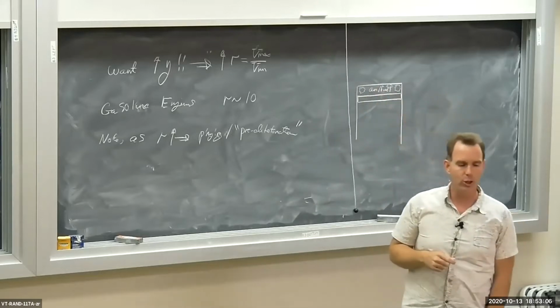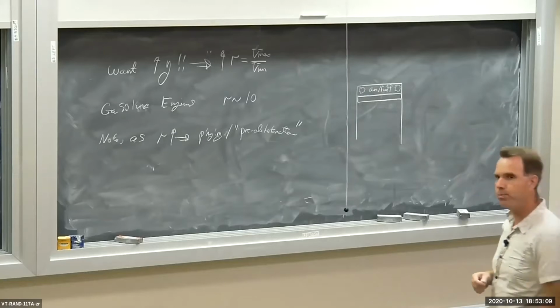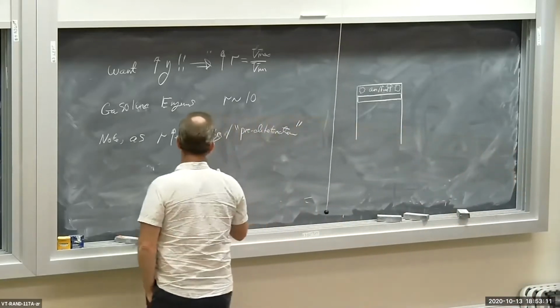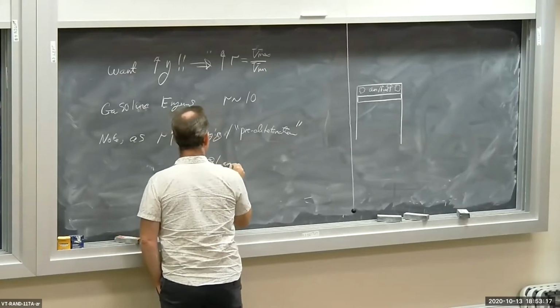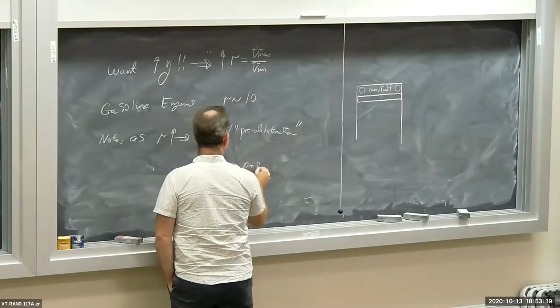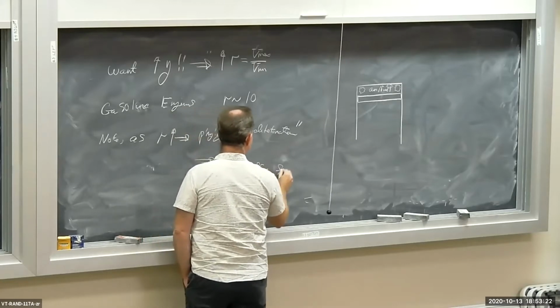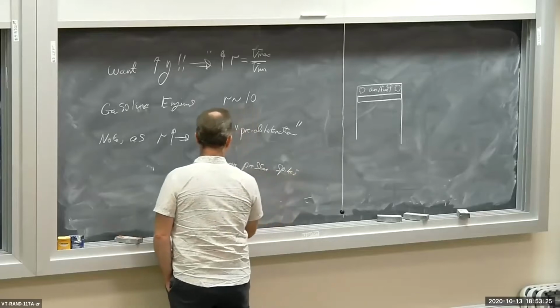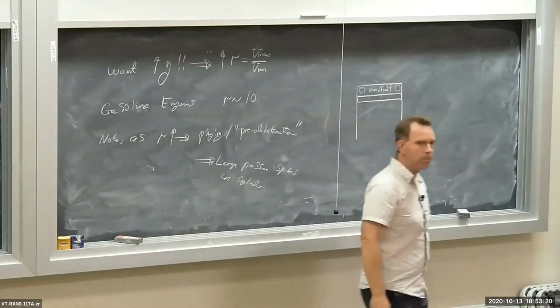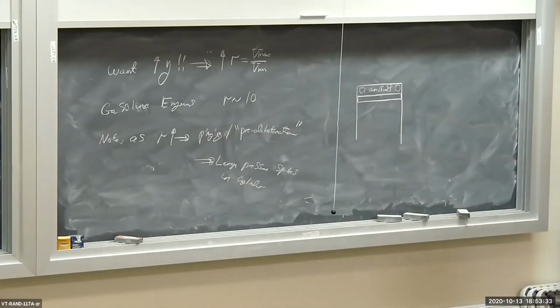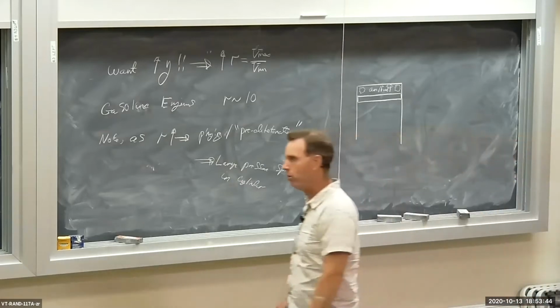Then these flames grow and they hit each other. The flame fronts hit each other and produce very large pressure spikes. So if you get pinging and pre-detonation, you get large pressure spikes in the cylinder. And those pressure spikes, actually you can hear them, called pinging. The engine will make a ringing sound or a knocking sound. So you get large pressure spikes in the cylinder, and that will do damage to the engine, mechanical damage.